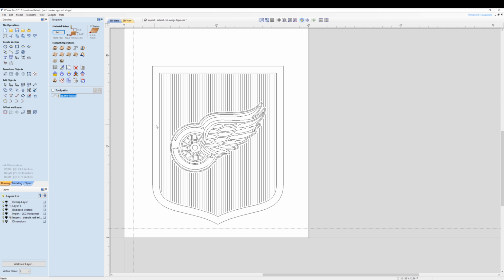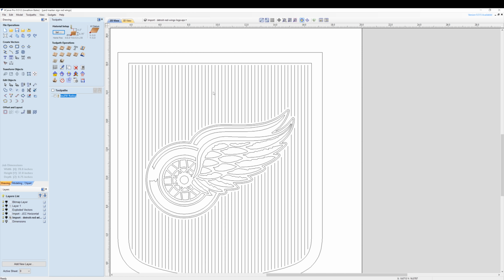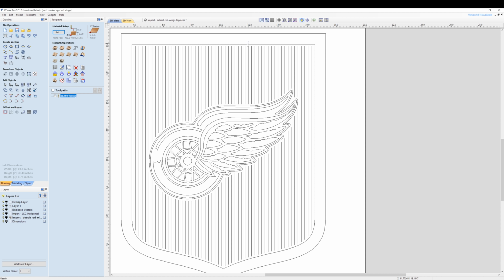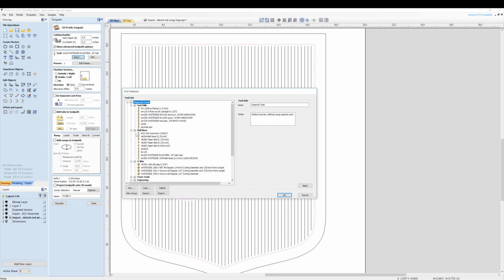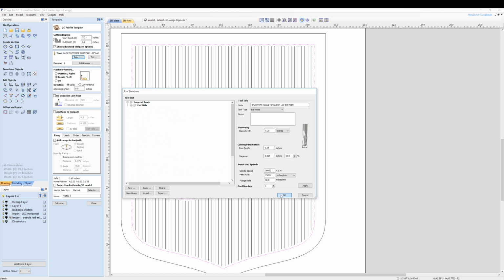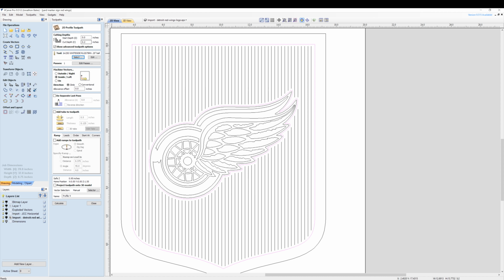Next up, we want to clean up the ends of the fluting on, well, both ends. So what I'm going to do here is select this profile and select this outside profile. And we're going to do a profile toolpath, depth of 0.2 inches. And we are, let's see, the Whiteside 1/4 inch ball nose, same aggressive 150 inches per minute. It's going to plow right through it. Let's press OK. Same cutting depth, which is 0.2 inches for the fluting. And we're going to go on the inside of these vectors.